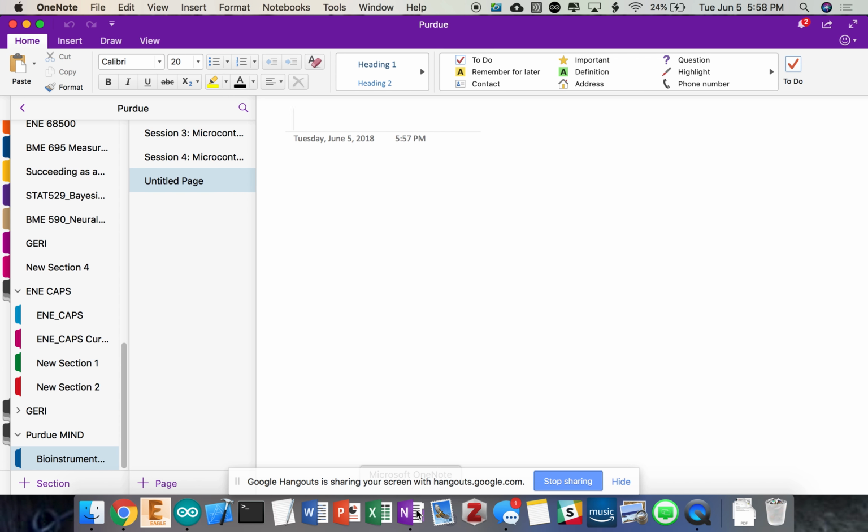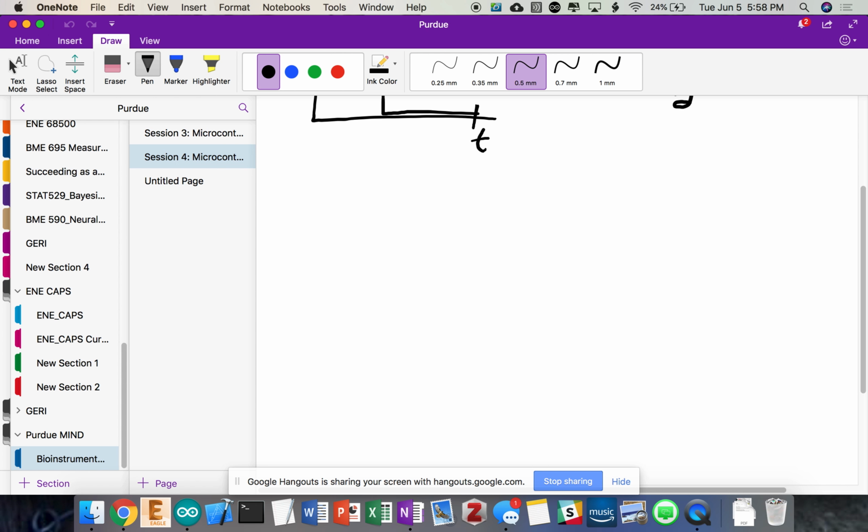You should also know the frequency. No one really ever talks about the frequency of the waves so much, but on the UNO, the frequency of the PWM signal is typically 490 hertz. On the SAMD21 it varies, but I think it's somewhere on the order of 790 hertz. It's just fast enough so that it looks like you can average the signal over time.